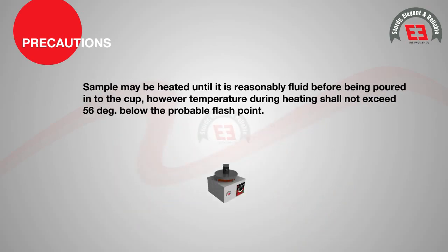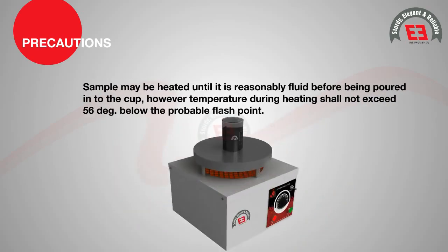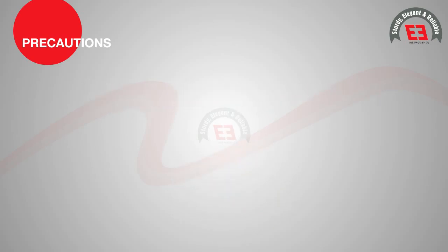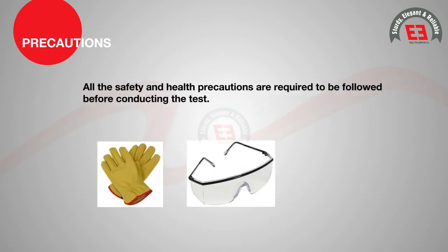Sample may be heated until it is reasonably fluid before being poured into the cup. However, temperature during heating shall not exceed 56 degrees Celsius below the probable flash point. All the safety and health precautions are required to be followed before conducting the test.